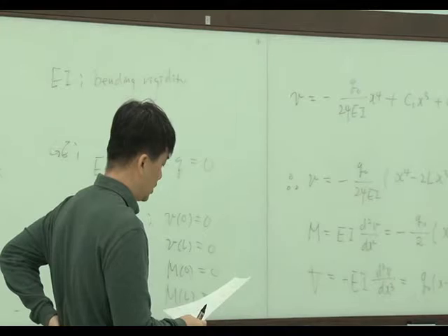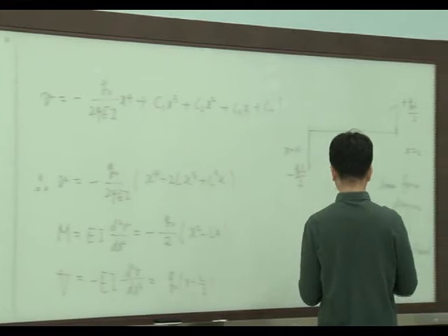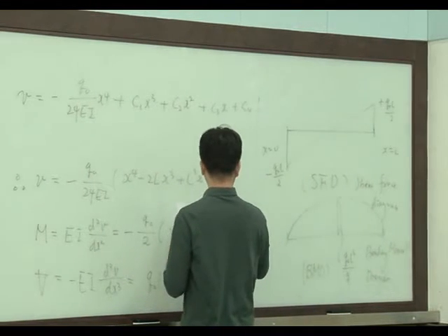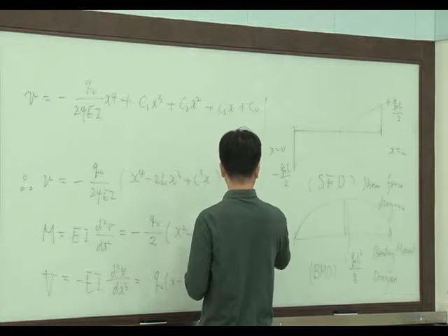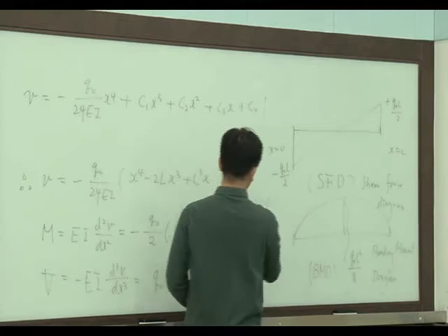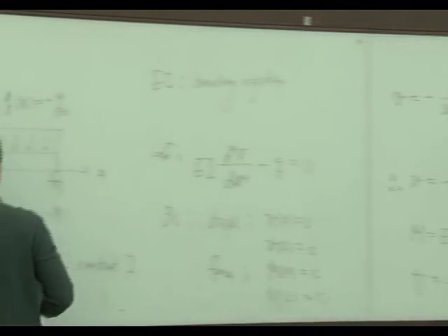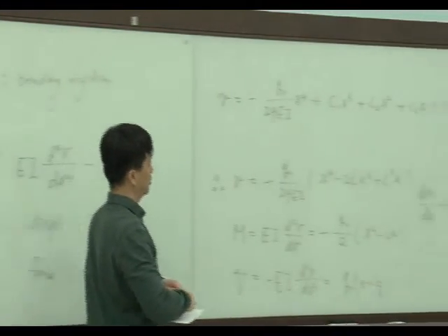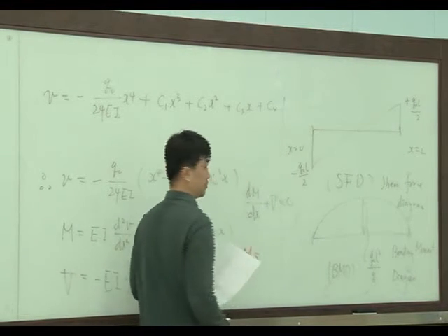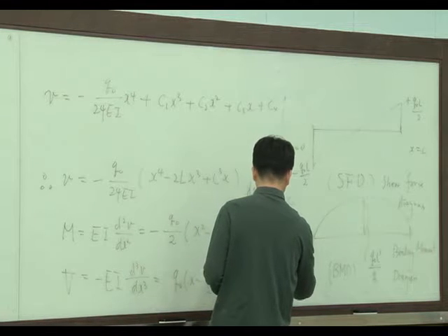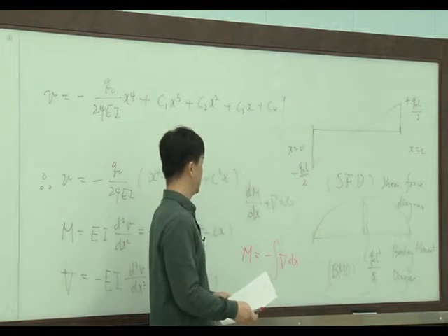Actually, we know the relation between shear force and bending moment. This was a relation from the equilibrium equation: dM/dx plus V equals 0. You remember this equation? So M equals minus the integration of V, right? This is the relation.